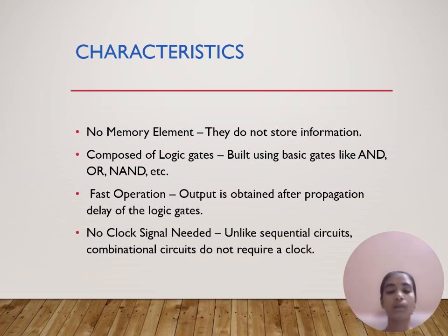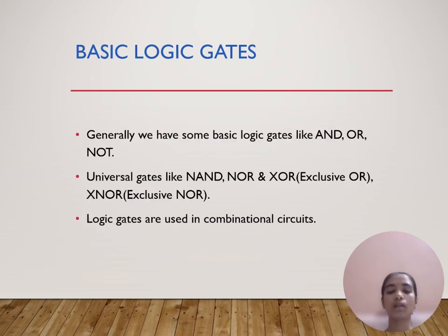Characteristics. No memory element. They do not store information. Composed of logic gates built using basic gates like AND, OR, NAND, etc. Fast operation. Output is obtained after the propagation delay of the logic gates. No clock signal needed. Unlike sequential circuits, combinational circuits do not require a clock.